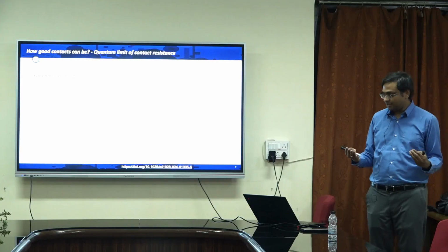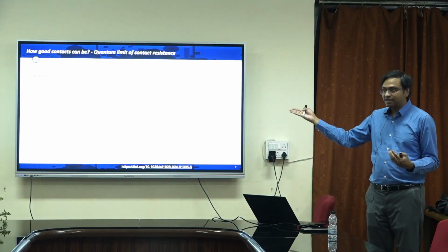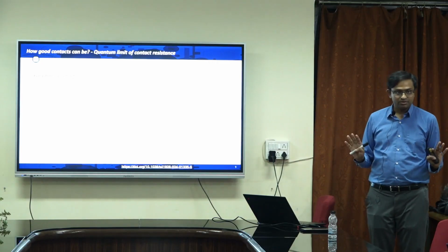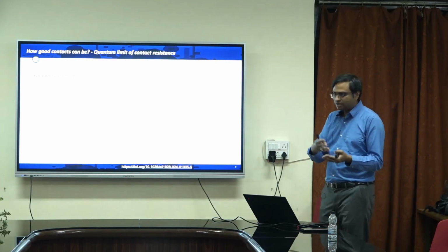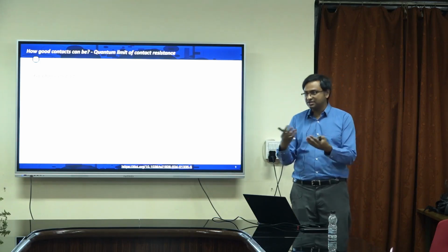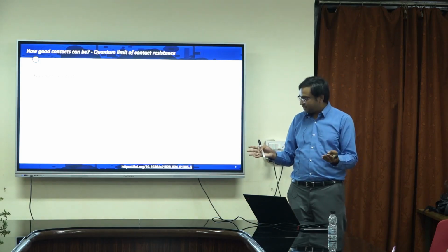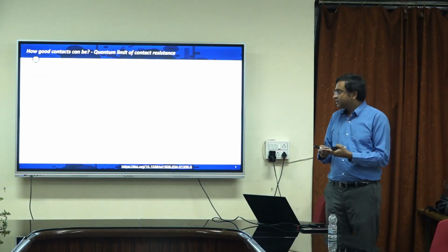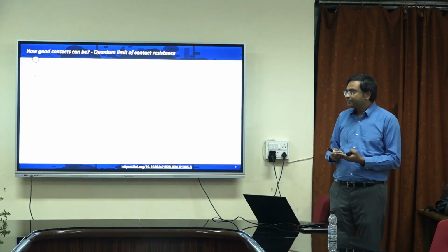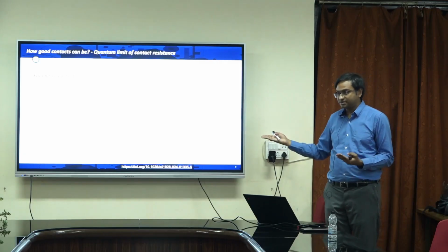If you dope your channel, right, then also you can get different N2D, right? Carrier concentration you can change either by doping it, like for silicon we dope it with phosphorus, arsenic, boron, right? Or you can do it by applying gate bias electrostatically, right, which happens in a transistor.